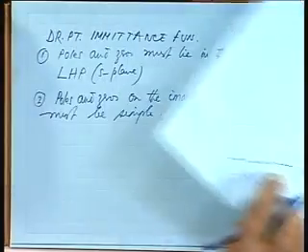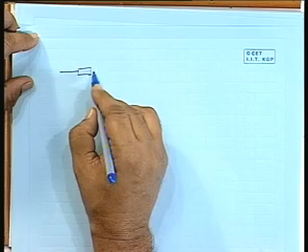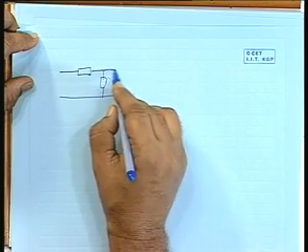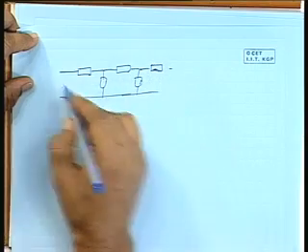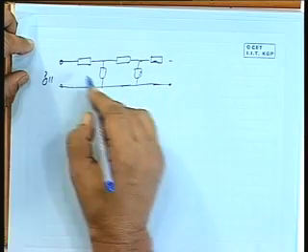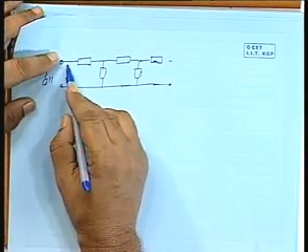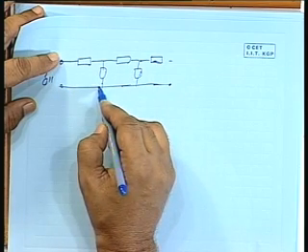Another thing, when we talk about RLC elements, see both these admittance and driving point admittance and impedance functions, they are after all obtained by some combinations of network elements like this. Suppose you want to measure Z11 driving point impedance, then keep it open and then measure the impedance, is it not? While measuring the impedance, you take this plus this and parallel combination of this and so on.